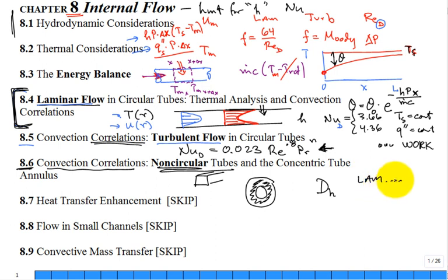They have worked out a lot of analytic solutions, and we'll show in a table. But for turbulent flow, it's kind of like, okay, get the hydraulic diameter and then go use the round tube correlations. Go use that Dittus-Boelter, that 1930s version of a correlation. All right. What about heat transfer enhancements?